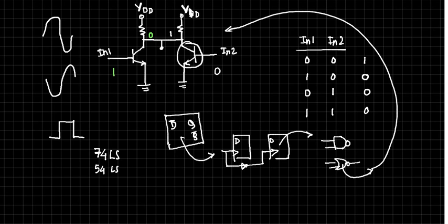Schottky, have you heard of it? Schottky diode. So the Schottky diode is actually preventing... so let me write that, low power Schottky. This Schottky diode is nothing but it is used for transistors to avoid the saturation condition. In that sense, it will never allow the transistor to go into saturation. Like the transistors would operate below saturation levels. So we'll see the structures.